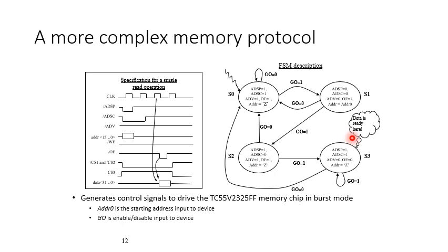So what is burst mode? Burst mode means that we are reading in pipeline. I have already told you what pipelining is. So we are reading the data in pipeline. The input to our machine is clock. So to this finite state machine, the input is clock, and the starting address, which I have already told you is addr 0, and the enable disable signal, that is go.